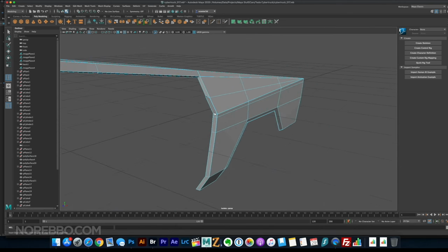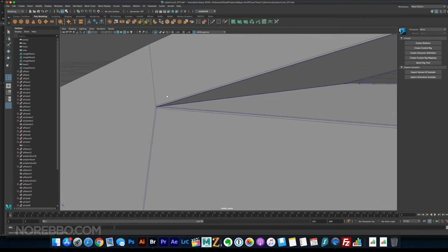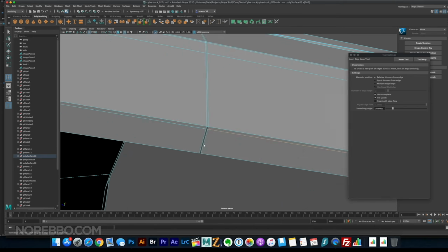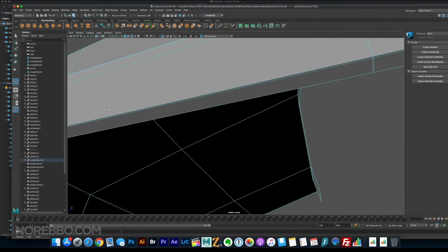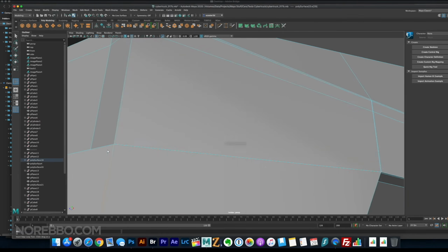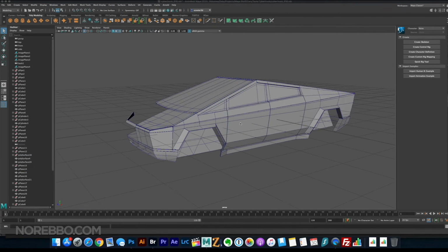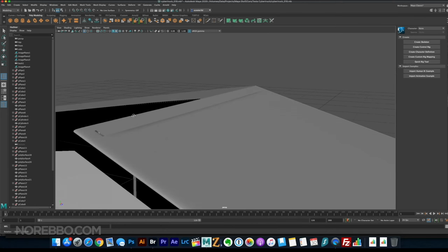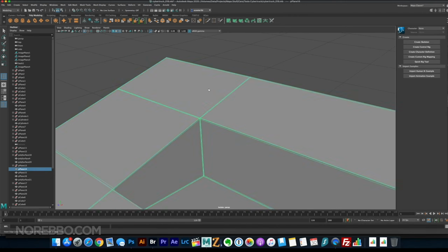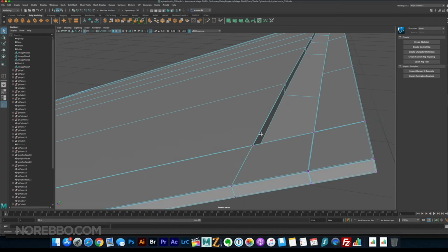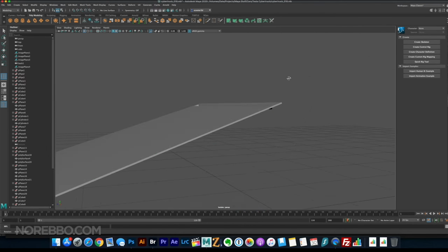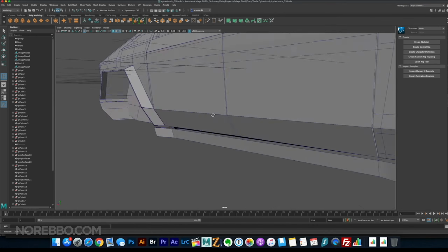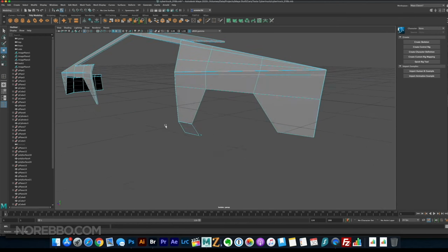But yeah, so what have I got going on here? Trying to reshape a few things, adding. I remember totally. So the Tesla Cybertruck is very angular, and like I said, I was trying to build a smooth model. I wasn't going to leave my polygons unsmooth. I really wanted to smooth everything out, and that was a pain in the butt, trying to get everything sharp in the corners. I should have just left everything as raw polygons and beveled where necessary, instead of trying to add edge loops and trying to smooth everything. Lesson learned, totally. And that was something that I fought with for a very long time on this particular model, and it was frustrating to say the least.